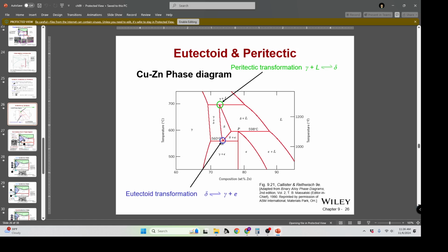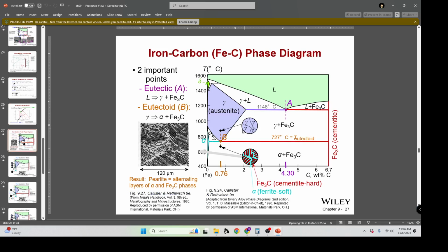So the iron carbon diagram gets much more complicated, and there's a lot to this. So again, that's a lesson worth going back to review in great detail, talking about pearlite. So you have both a eutectic point and a eutectoid point. Above the eutectoid point, you have just austenite. So a lot of steel processing and manufacturing happens in this box here, usually at or above the eutectoid point for at least what are considered to be higher carbon alloys.